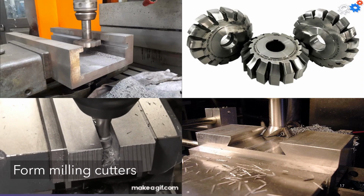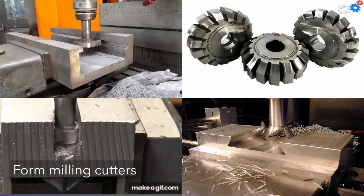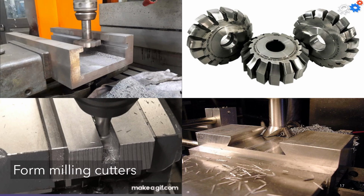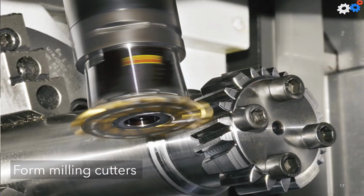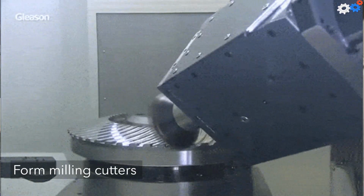The form milling cutters are peripheral milling cutters in which the cutting edges have a special profile that is to be imparted into the work. An important application is gear making, in which the shape of the milling cutter is to cut the slot between the adjacent gear teeth, thereby leaving the geometry of the gear teeth.